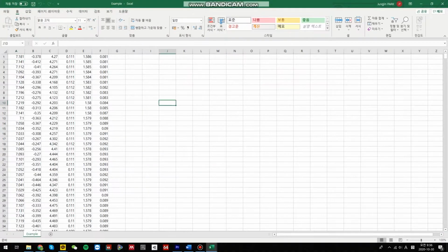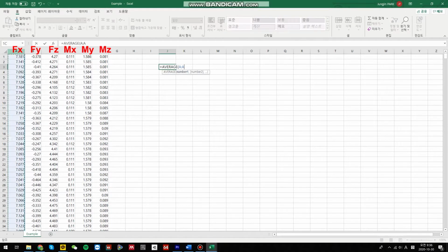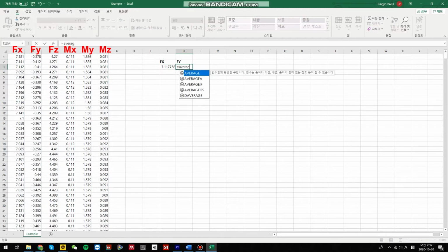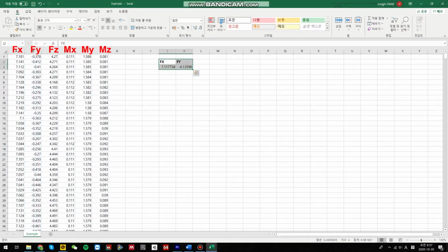So if we load up our data from the first angle that we tested here on Excel, you see 6 columns, which are for the 3 forces and 3 moments, and 1,000 rows for the samples that we took. We can simply average each column to get the average lift force and average drag force from those 1,000 samples. And I already did this for all the test data files for your project, which you can find as a spreadsheet on Canvas.